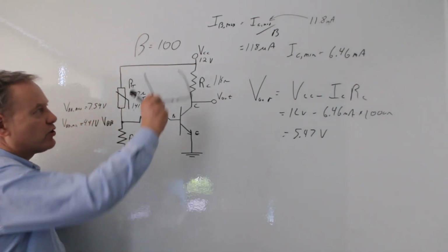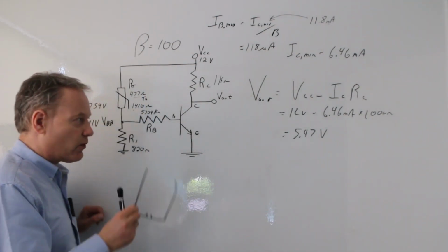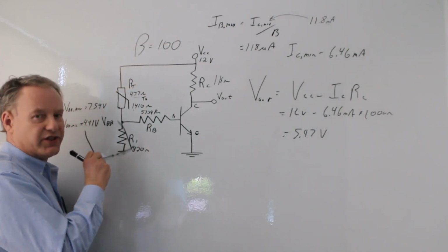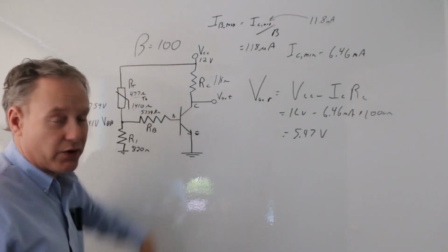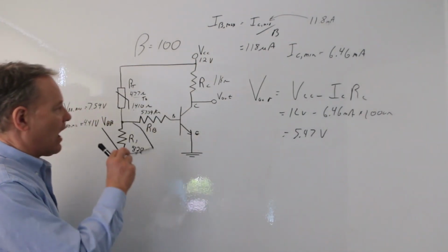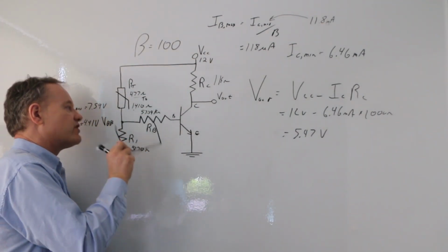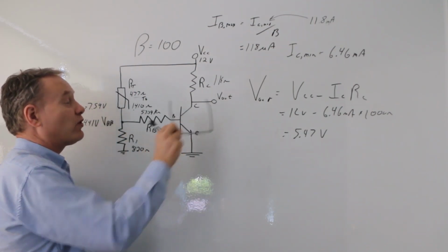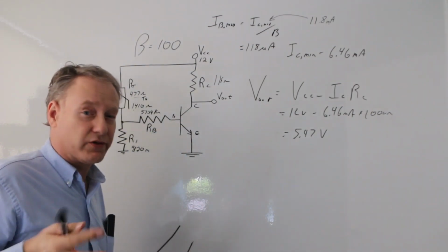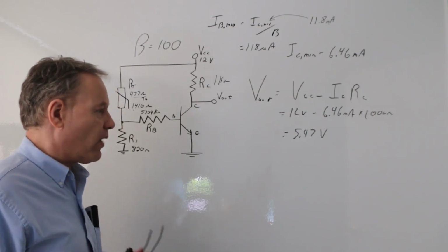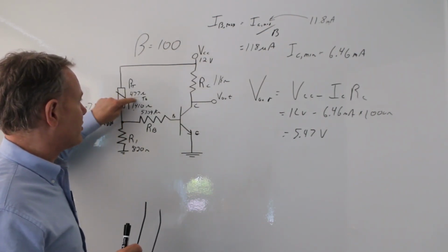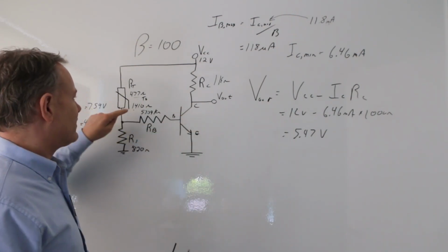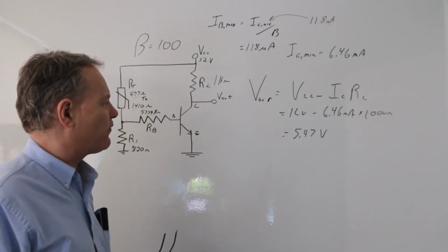We looked at how much current we needed, and then we said, okay, if I have these two voltages here and I know my maximum voltage is going to be saturating this thing, then I have to calculate the right resistor here to fully saturate that, so that my voltage out is going to be 0 volts or 0.2 volts. So when this thing is at its minimum temperature, I'm going to get 0.2 volts out. When it's at its maximum temperature, I'm going to get 5.47 volts.